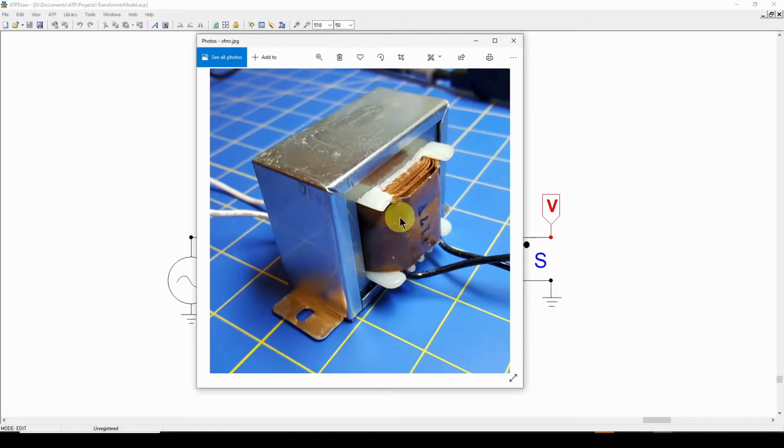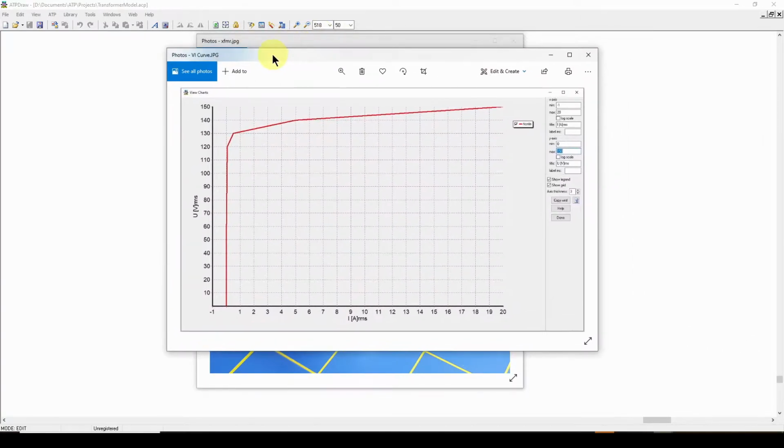And in the previous video, we made some assumptions and guesses about what we saw was the nonlinear characteristic of this transformer. And we came up with a model that we input to our computer simulation. Again, we can simulate these transformers in LTSpice or Matlab Simulink, whatever simulation software you want. In this case, we're going to use software called ATP, since it makes it, in my view, a little bit easier to look at nonlinear characteristics.